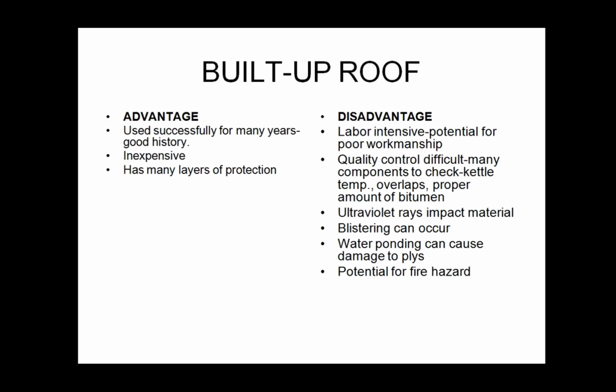The built-up roof is the next potential choice. It's a fairly typical roofing design and construction. It's pretty inexpensive, and what it does, it's built up. It has a lot of layers of protection, so you're covering yourself by including many layers. The disadvantages are obviously if you're going with multiple layers, you've got more workmanship, more costs in material most likely. Sometimes quality control is a little bit difficult because you're hiding layers underneath other layers.